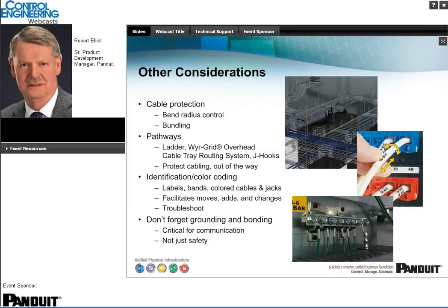Other considerations that you might need to consider, obviously the cable bend radius control, that's critical in the installation. That always has to be looked at. The bundling of cables, how they're routed within pathways. What type of pathways are you going to use? Ladder rack, wire grid, is it overhead, is it underfloor, is it suspended in J-hooks or rated in conduit, so it's protected and out of harm's way.